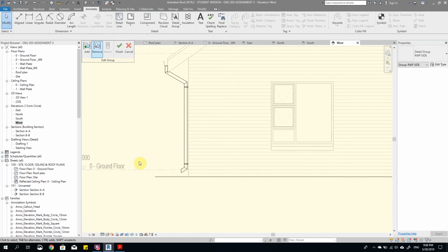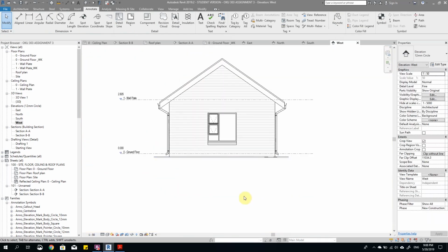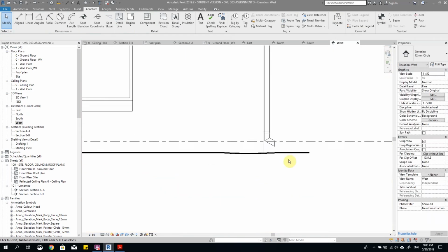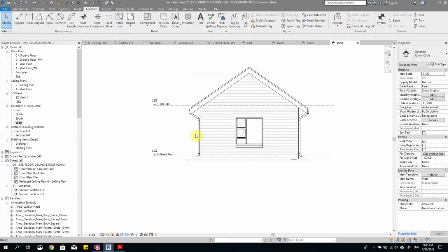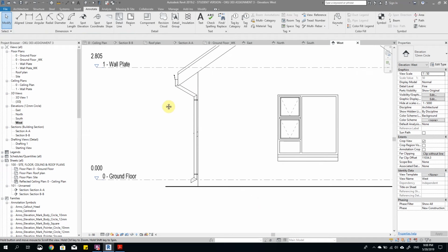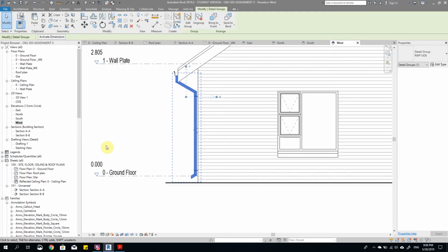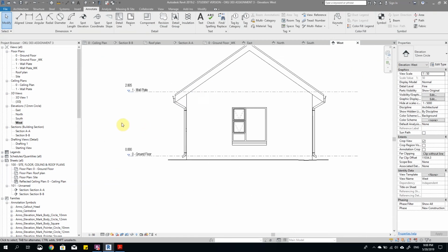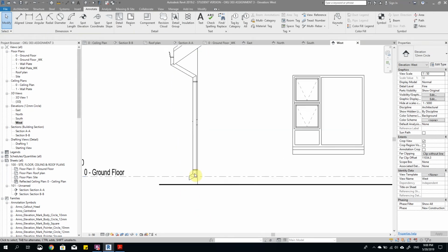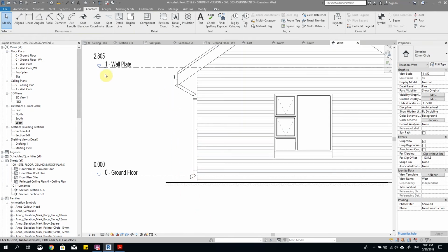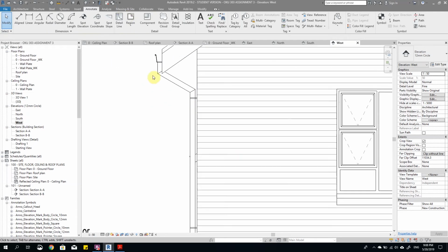Done. Excellent. Finished. Okay, that will work. Alright, so the water spills out below the DPC. Alright, that's great. Okay, the next thing we need to do is I need to create a gutter front. I'd much rather create it in this view, so I can use this one to kind of get everything right. So what I'll do now is I'm going to go to filled region.